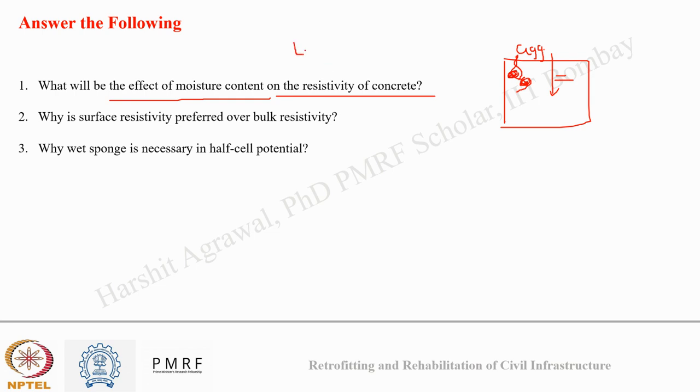There will be several literatures which comment on the relationship between resistivity versus relative humidity of concrete. As the moisture content in the concrete increases, my resistivity value decreases.